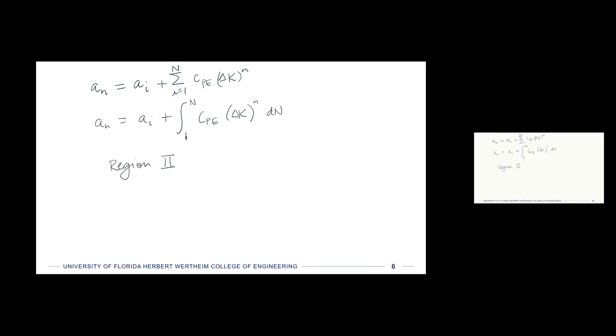And that says in the book, it gives us a really nice range. So it says that in this region, for most engineering materials, da/dN is kind of 10 to the minus 3 down to 10 to the minus 6 inches per cycle. Right, so 10 to the minus 3 inch is 1/1000th of an inch, which is sometimes referred to as a mil in machining language. So if you have any experience with that, and then down to 10 to the minus 6 inches. So every cycle can be in that range, and that's the stable range.